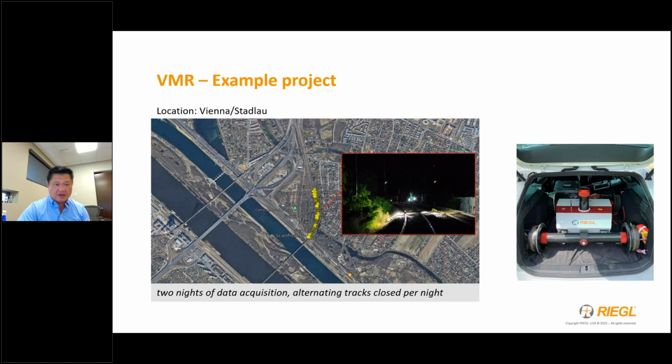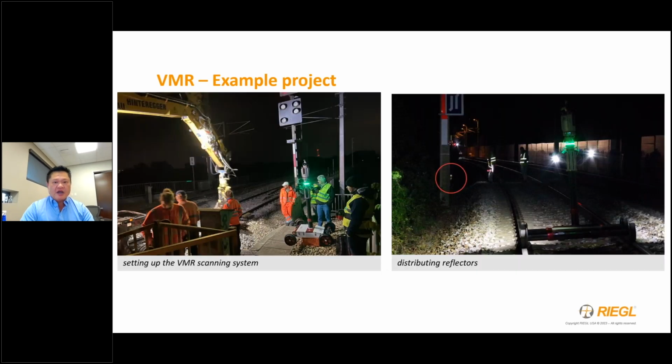I love how-tos, right? So here you can see the highlighted target. You don't have to say, hey, scan, because our scanner can detect targets automatically. On the scanner, in the workflow, you just define the type of target you're using, whether it's a cylindrical target or a flat target, or now, of course, the black and white checkerboard pattern target. It'll stop, and if there's a target within range, it'll scan and pick it up automatically.